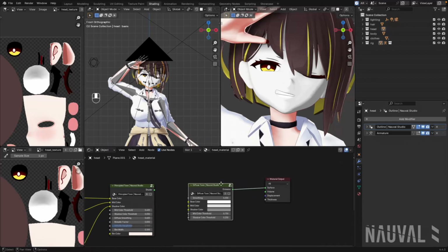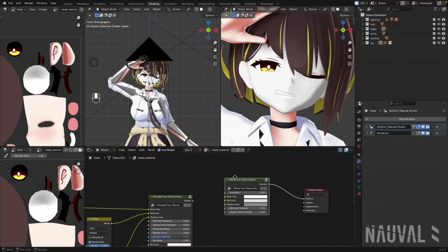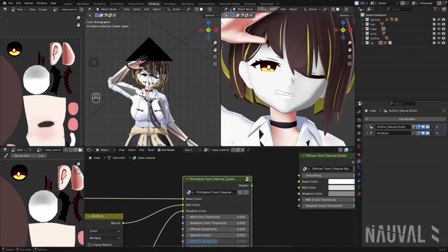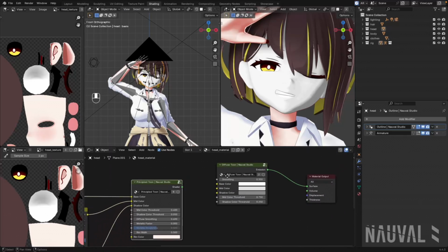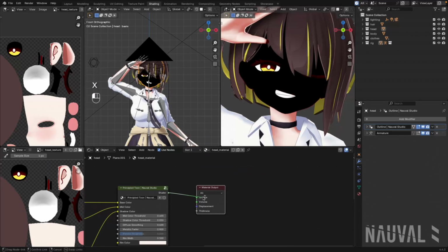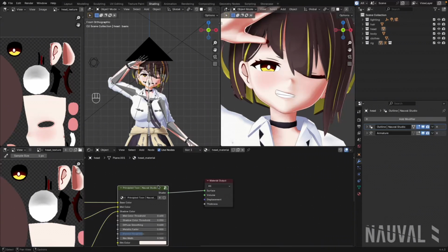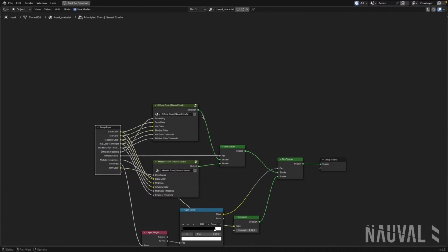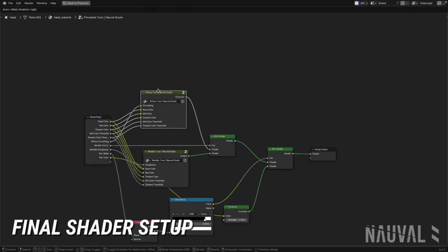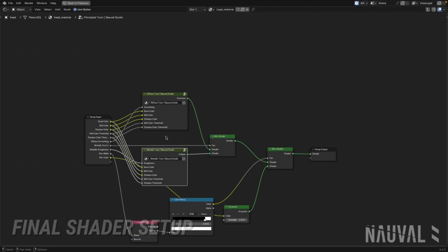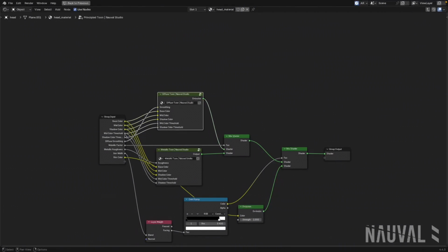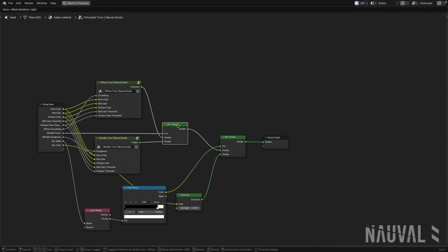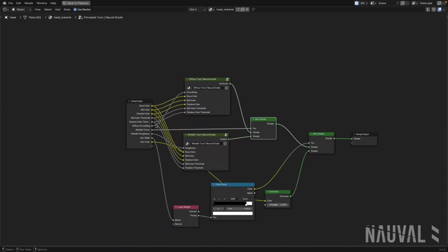And then we use this diffuse Toon and the metallic one to create this single principled Toon custom shader. Just connect it again and preview the node. As you can see here, it uses this diffuse Toon and the previous metallic Toon, and uses the input from this node and mixes them together using this metallic factor.